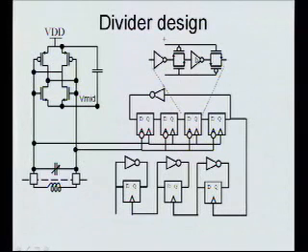Now the reason this is low power is that the switches are effectively differential, and they're being driven by my oscillator. And my oscillator is high Q. So all the capacitance associated with the switches is being tuned out by the inductor. And so I get an effective power reduction of Q. It's not quite that good, but it's very close to. And so then the only power I'm consuming is to switch 2 inverters per cycle of my oscillator. And only one of those is switching high. So in effect, you're only consuming 1 inverter worth of switching power per cycle of my oscillator.